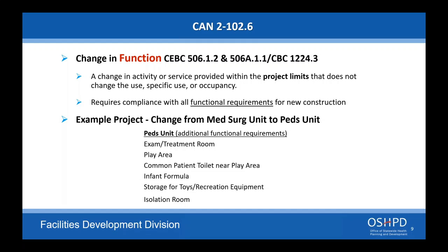If during a repair project, due to water intrusion, an existing non-compliant condition is discovered, PVC above ceiling, does a facility need to address the non-compliant condition? If it's existing non-compliant, they do need to address it. Again, if you're doing a repair project, is it part of the repair? It would need to be replaced.